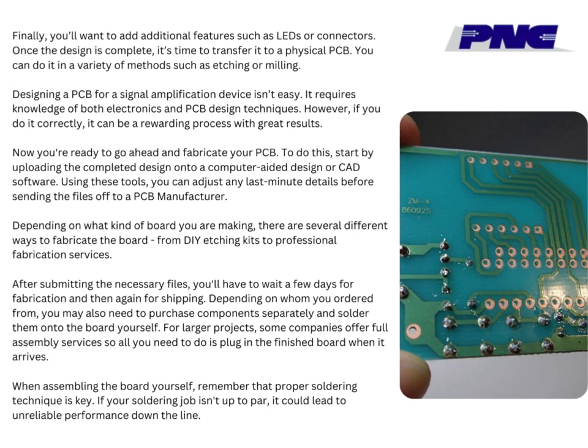After submitting the necessary files, you'll have to wait a few days for fabrication and then again for shipping. Depending on whom you ordered from, you may also need to purchase components separately and solder them onto the board yourself. For larger projects, some companies offer full assembly services, so all you need to do is plug in the finished board when it arrives. When assembling the board yourself, remember that proper soldering technique is key. If your soldering job isn't up to par, it could lead to unreliable performance down the line.